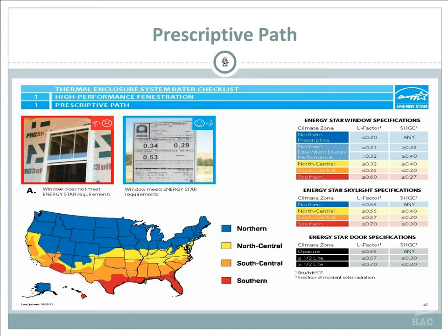If you're going with the prescriptive, we're talking you're going to be above Energy Star. So these are some of the things that you can look at from the very beginning. I just threw in the windows so you can see the different U values that they use for windows. They changed this from R values to U values. For those of you that are new to U values or not sure what a U value is, a U value is the coefficient of transmission, okay? So, for example, the transmission of heat through materials which compose a building's envelope or outer shell. In this particular case, we're talking about the U value of a window, okay?